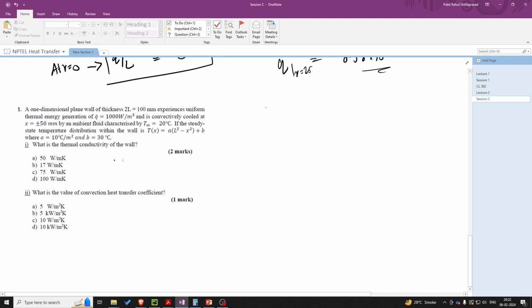So that will give you the heat generation equation along x as this term del 2T upon del x2 plus q dot upon k is equal to 0.